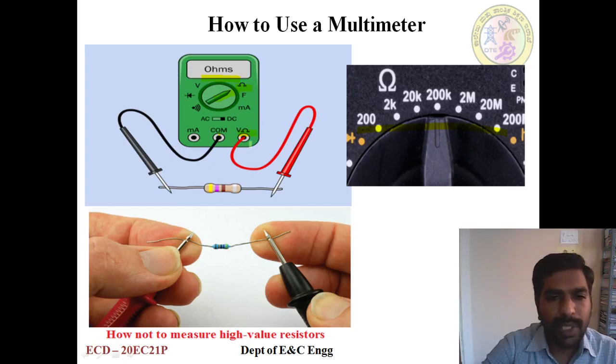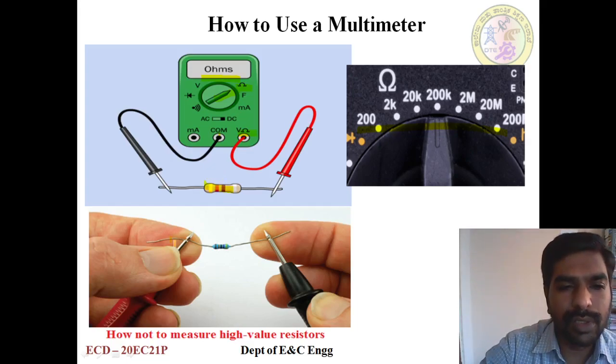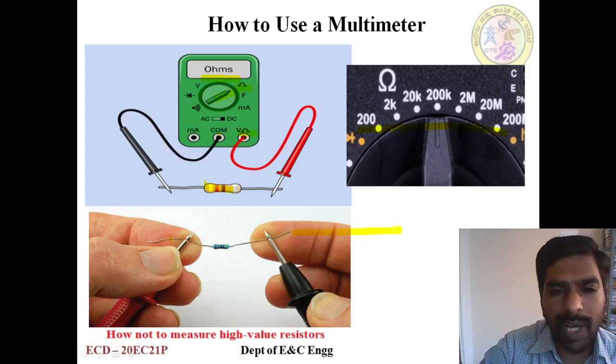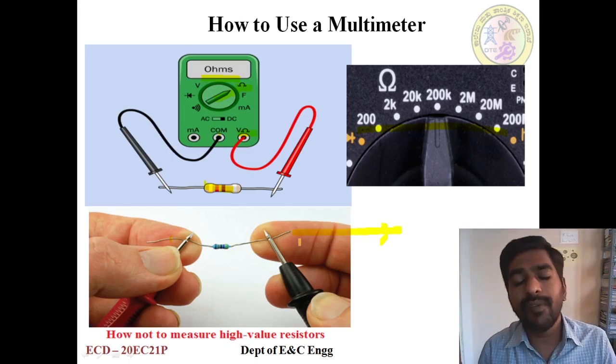And while measuring the resistance, we cannot use our hand like this to measure the resistance, because it will not give an accurate result, because our body also has an inbuilt resistance.